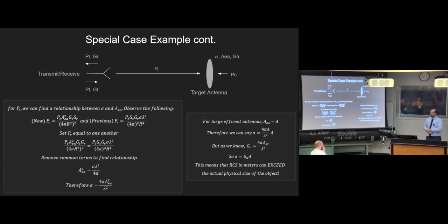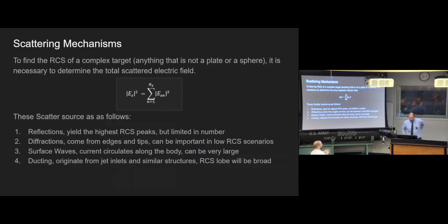This is the problem that the Su-57 has run into. It actually has the radar cross-section of a Boeing 737. A 5th generation fighter. All right, so that's an important thing. If anything that you take away from this, take away that higher frequencies can result in magnified RCSs. Simple relation, super important. That's the single most important thing to remember, because if you mess up doing your math, applying the coating, someone scratches it, you can have a huge problem when your plane gets shot down and you lose your pilot, which is not good.